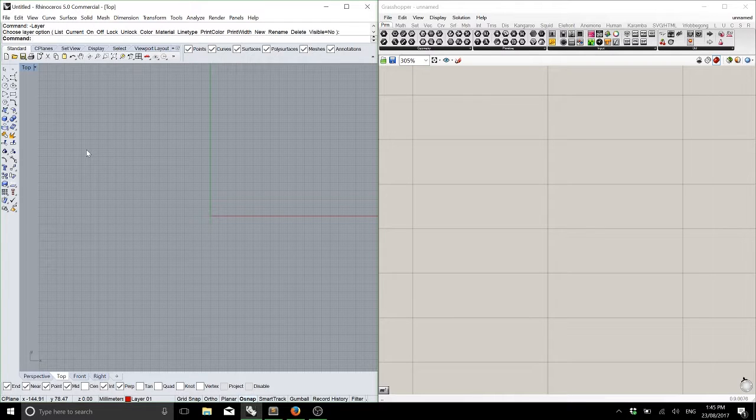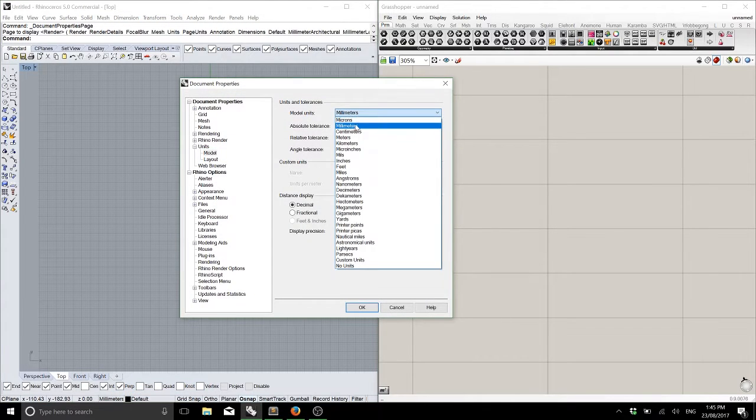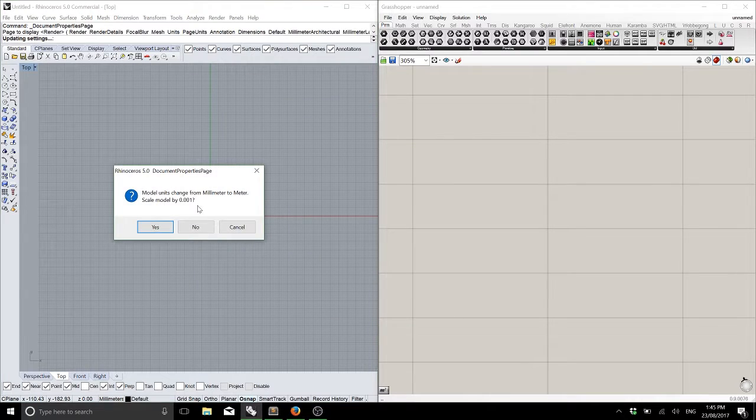Either way, you should be drawing everything on the default layer, and you can see at the bottom here, you can actually change the layer that you're drawing on with this little thing here too. So what layer are you drawing on at the moment? Default. Okay, so I'm going to do everything on default at the moment. For those of you who can add and change layers, please do so. But you're obviously limited to default and layer 1, 2, and 3. So I'm going to draw one room outline. I'm just going to make sure I'm in meters, because I don't want to work with large numbers at the moment.